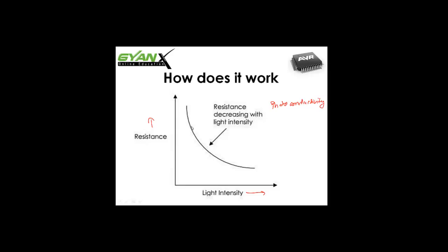When photons fall on the device, the electrons in the valence band of the semiconductor material are excited to the conduction band. These photons in the incident light should have energy greater than the band gap of the semiconductor material to make the electrons jump from the valence band to the conduction band. Hence, when light having enough energy is incident on the device, more and more electrons are excited to the conduction band, which results in a larger number of charge carriers. The result of this process is that more and more current starts flowing, and hence it is said that the resistance of the device has decreased. This is the basic principle of an LDR.